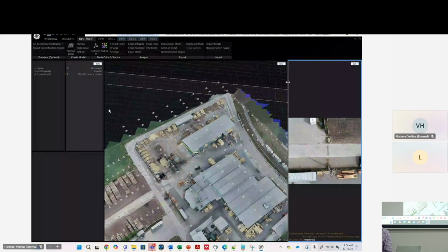You have to do it after densification because you need the mesh. Without the mesh, you cannot get the mapping and you cannot get where to project it, because you can project colors onto the point cloud, but you can't get a texture map unless you have a mesh. So a mesh is a prerequisite that you need. So, align, densify. Well, align, and then ideally you want to do the GCPs after that.